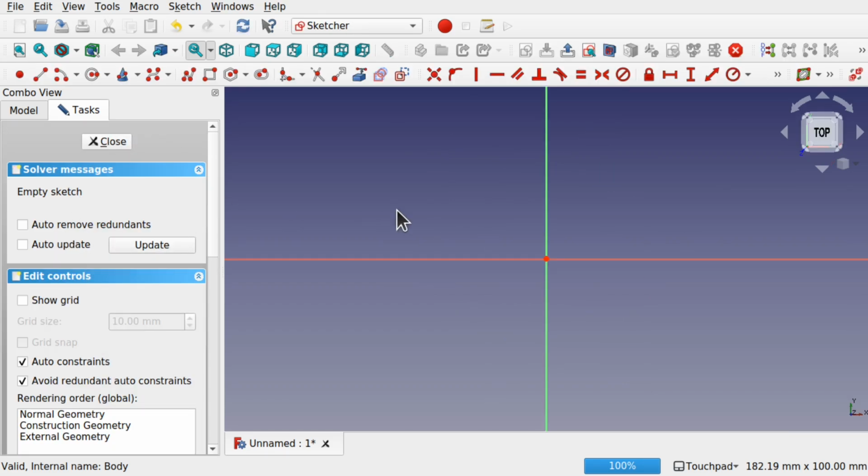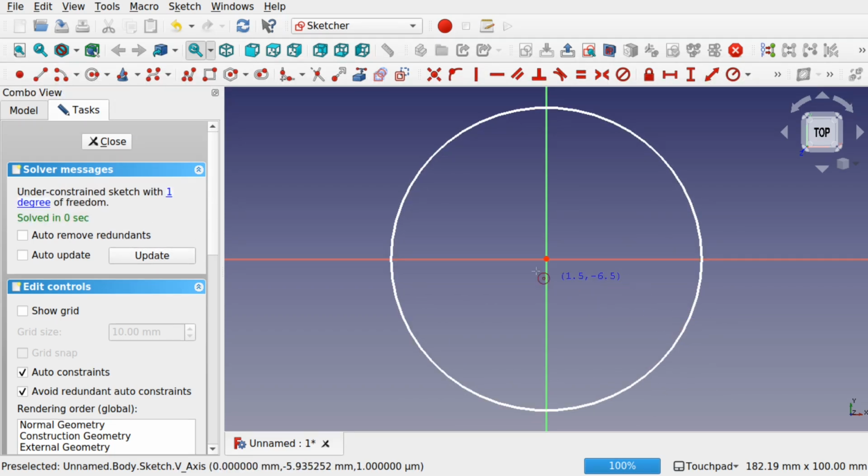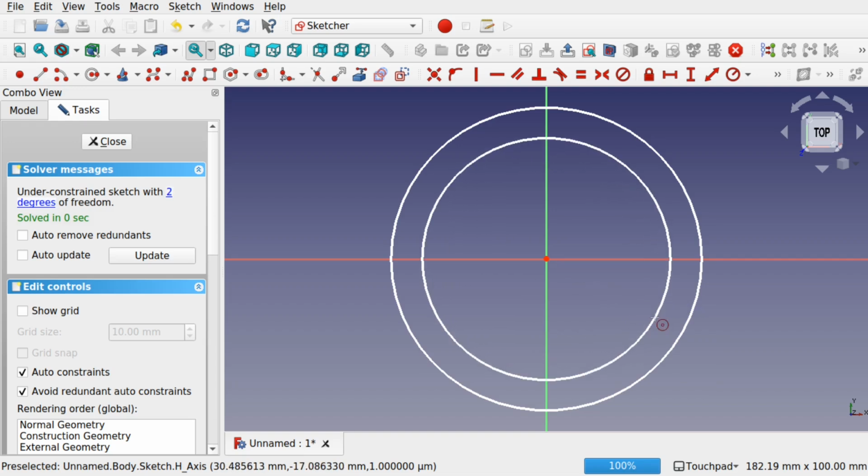Now to create a hollow loft we need a hollow profile. So that profile will basically have a skin. When I say skin, what we mean is that we have geometry like a circle, and inside we have additional geometry like so. So if I duplicate this up, it would actually create a loft between those two circles.